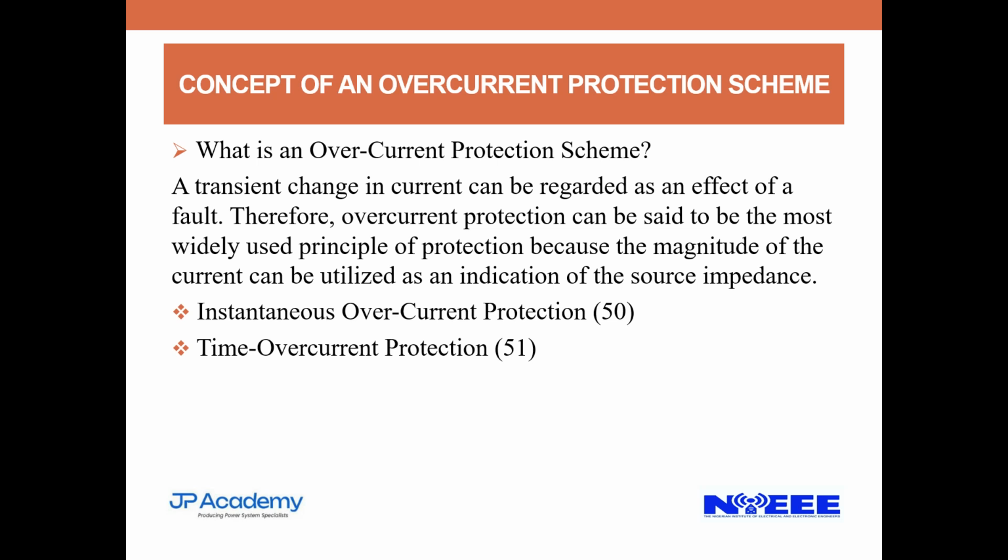In instantaneous protection, we are saying that in designing the protection scheme, we do not put any intentional time delay. There is no intentional time delay. However, there is time delay. Now, what causes this time delay? This time delay is caused by the relay operating time and the circuit breaker operating time.